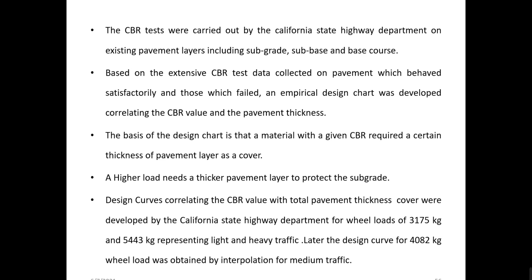Suppose, for example, I would like to quote, if the pavement thickness is very less, when are you going to expect the thickness of the pavement to be less? Wherever the CBR value of the soil is greater, then you can expect to have the lesser thickness of the pavement. Thereby the cost of construction of that particular pavement is going to reduce. Wherever the CBR of the soil is more, you can assume the pavement to have lesser thickness.